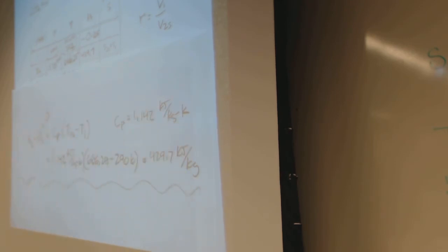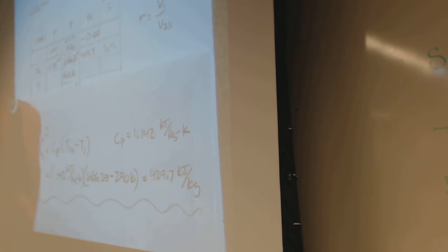And H3 minus H2S equals... now this is from 2 to 3, that's a constant volume process, so we're going to have to use a C sub V, constant volume specific heat. And we're looking for the value for T3. We have to use this value for H2S now.